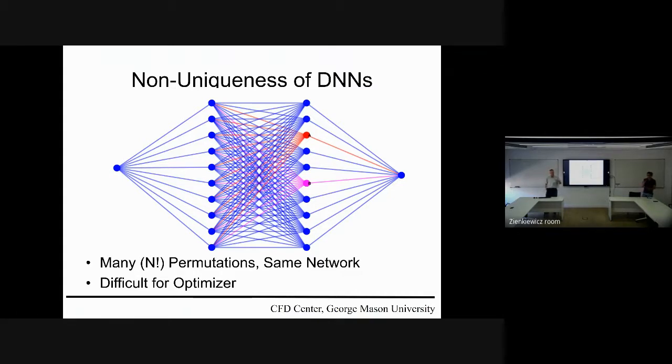You could relate it. Well, let's see. You compute the total surface that you have, and then you say I want to have 20,000 patches. There may be some surfaces that are smaller than that, so those you don't touch. That surface becomes one patch, so you cannot go below that. And even so, for example, if you have a surface with a certain area and you know that you were going to get 2 patches, you divide by 2. So you make 2 smaller patches. It doesn't have to be an exact size. And then you end up with some smaller patches in there. So I try to make them as uniform as possible.